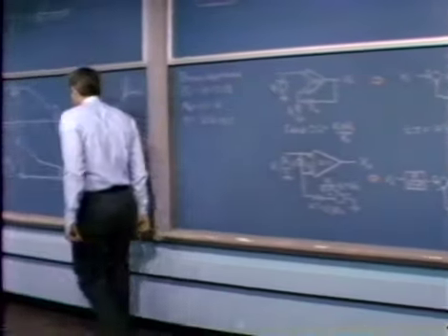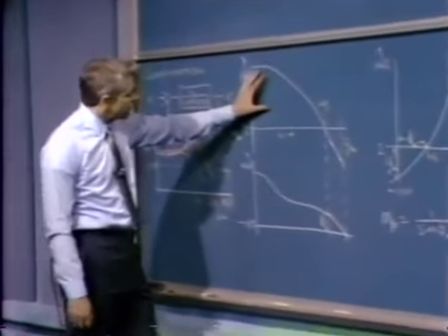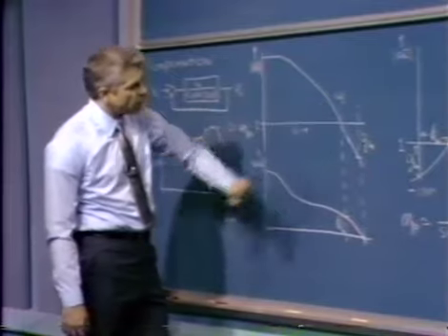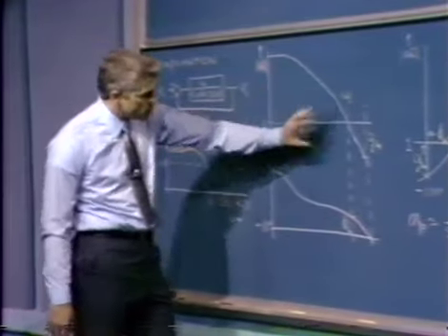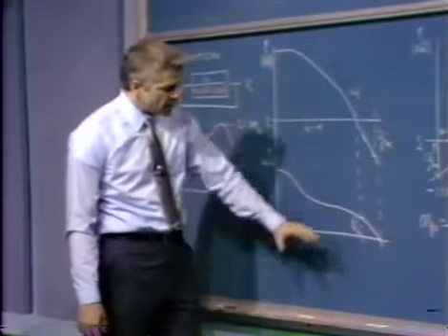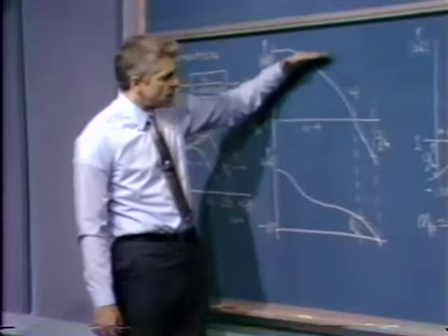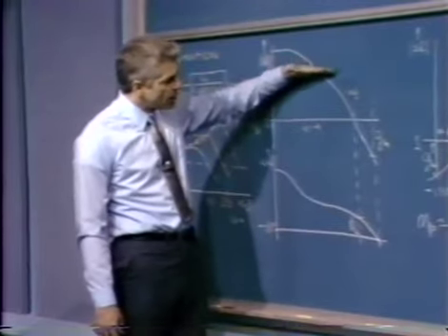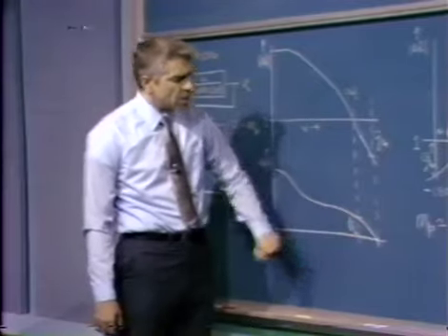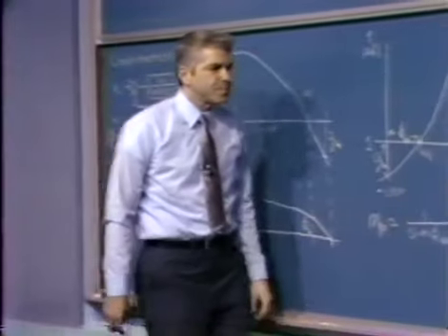We might believe that we have this kind of picture associated with the loop transmission, the very frequently occurring, well-behaved one where the magnitude drops off with increasing frequency and the angle drops off. In that situation, we increase phase margin as we lower crossover frequency. If we can attenuate the AF product without changing the angle characteristics, we get increasing values of phase margin as we push this curve down.